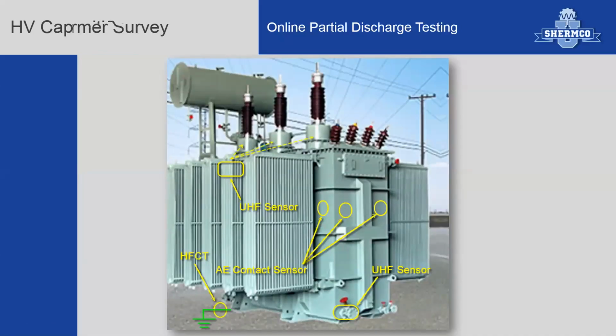Next I show surveying of a yard transformer. Here again, the UHF sensors may be used at the drain valve. I could potentially use them up where the bushings and seals are. Again, anywhere where possibly the ultra high frequencies can escape the metal and make their way back out airborne.